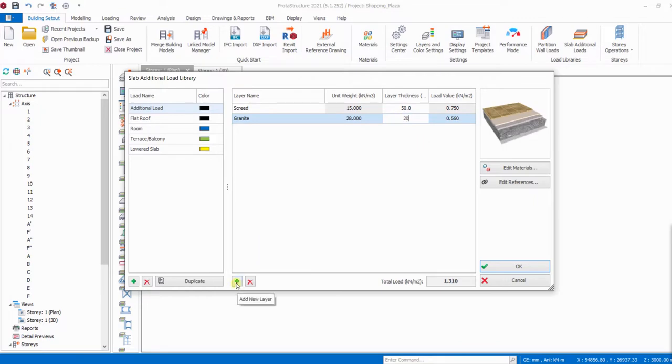So we are not done here. We add the MEP load, right, or the ceiling grouting. MEP load, because this one is just a shopping mall, we might not need MEP load, because MEP load, you'll be talking about the HVAC, you talk about the water for sprinkler and all of that. So that is additional load to the slab. So you add MEP load. All right. But we can go with this, or if we want to add more load, we can add ceiling grouting.